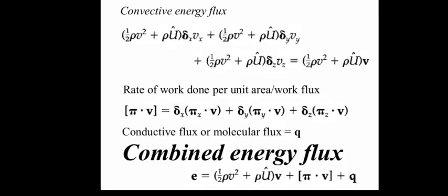In this specific case, we have Vx equal to 0 and Vy equal to 0. The x component will simplify to Ex equals τzx into Vz plus Qx, and further using a constitutive relation for viscous stresses, τzx equals minus μ ∂Vz/∂z, and Fourier's law, Qx equals minus k ∂T/∂x, leading to Ex equals minus μ ∂Vz/∂z into Vz minus k ∂T/∂x, where μ is the viscosity and k is the thermal conductivity.